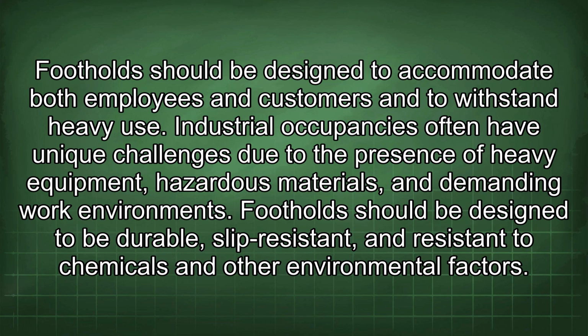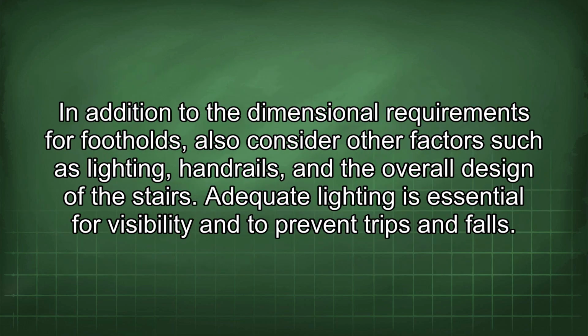Industrial occupancies often have unique challenges due to the presence of heavy equipment, hazardous materials, and demanding work environments. Footholds should be designed to be durable, slip-resistant, and resistant to chemicals and other environmental factors. In addition to the dimensional requirements for footholds, also consider other factors such as lighting, handrails, and the overall design of the stairs. Adequate lighting is essential for visibility and to prevent trips and falls.